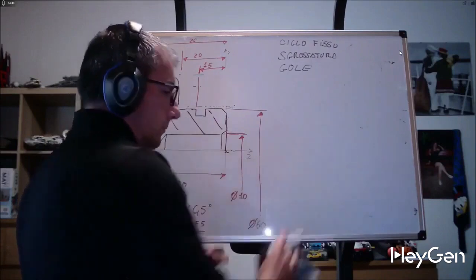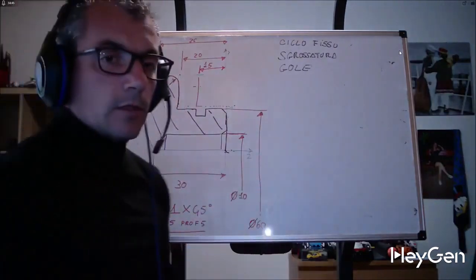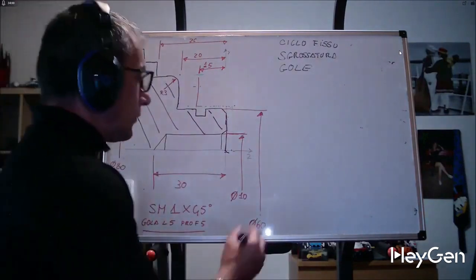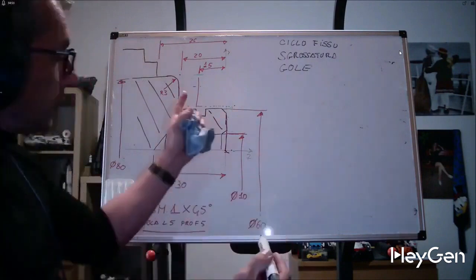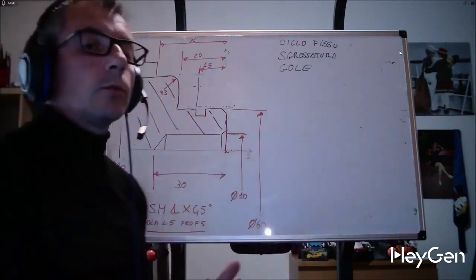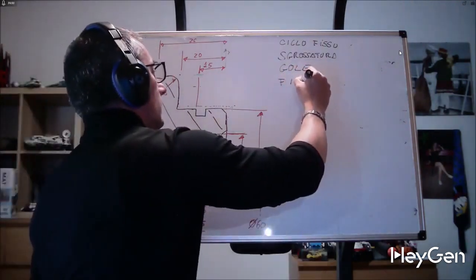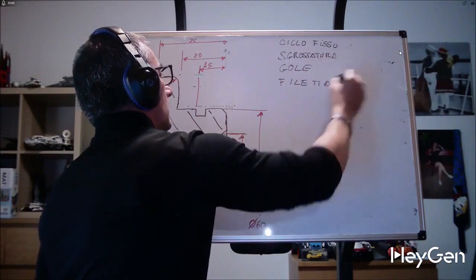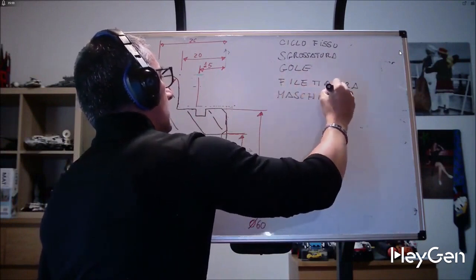However, if you have a front or wide groove of 30 mm to make with a tool of size 4, 5 or 6, a fixed cycle will definitely be useful. Once you have determined the width, depth and position of the groove, it will clear it for you, breaking the chips. Then there is the fixed cycle for threading, tapping, and drilling.